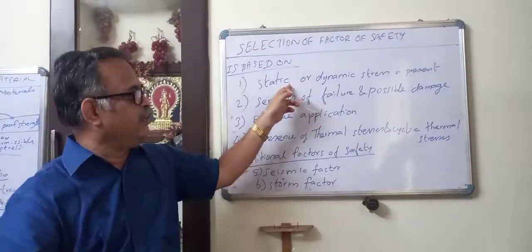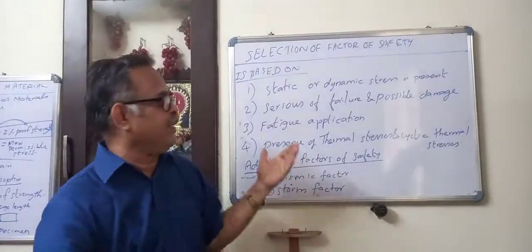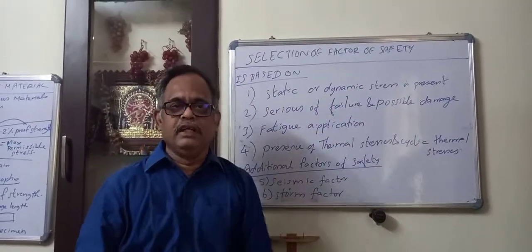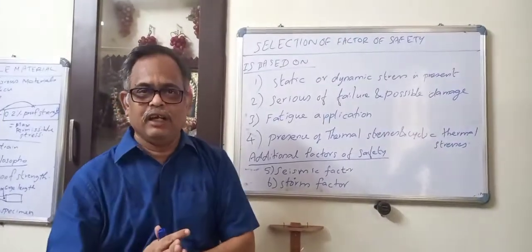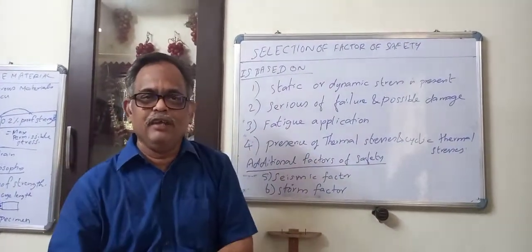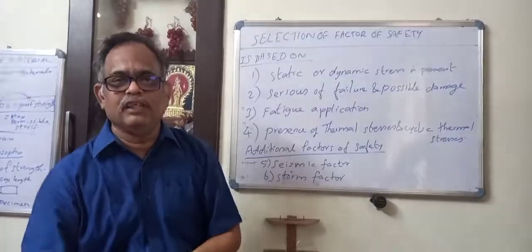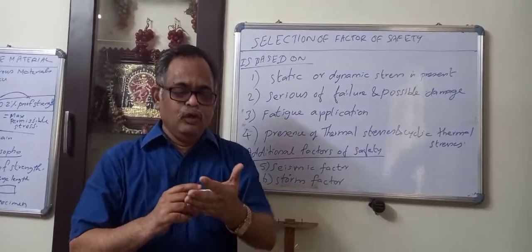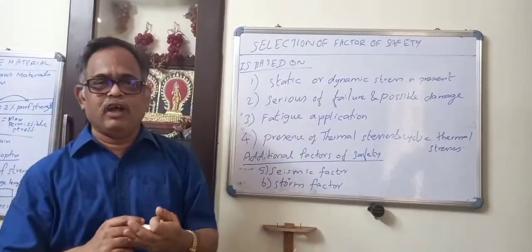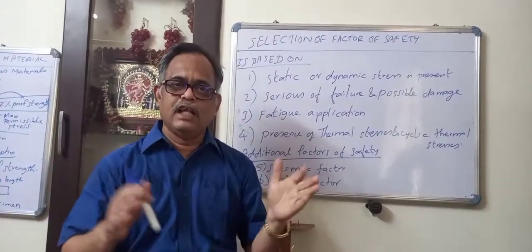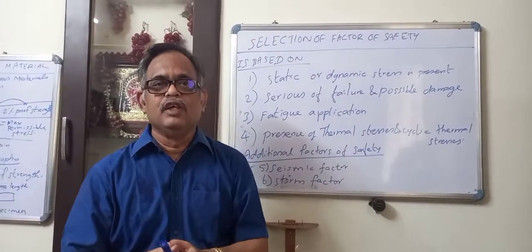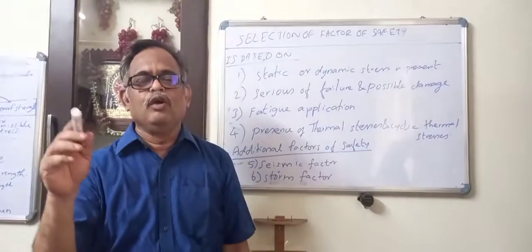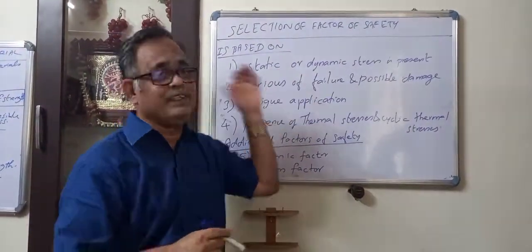Some arbitrarily, like 0.9 or 0.8, something like that. And then if in case dynamic stress is there, for example, a crusher may be running, which may be loaded onto a steel structure like that. In such a case, whatever factor of safety you are deciding for static condition, if the same structure is used for dynamic conditions, then what you can do is multiply the factor of safety.